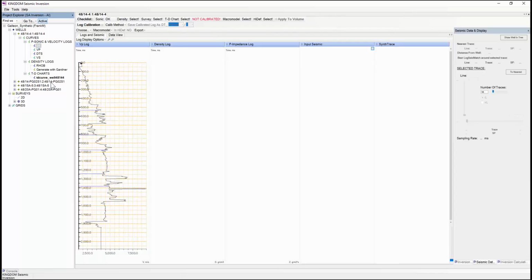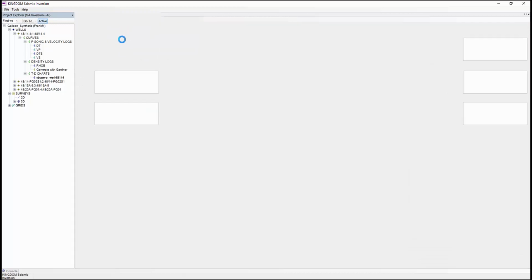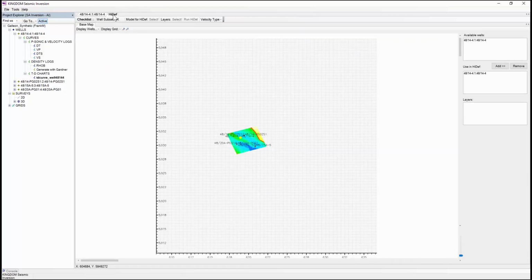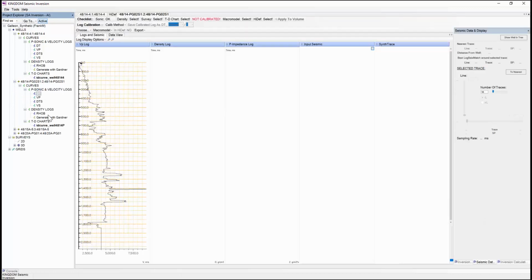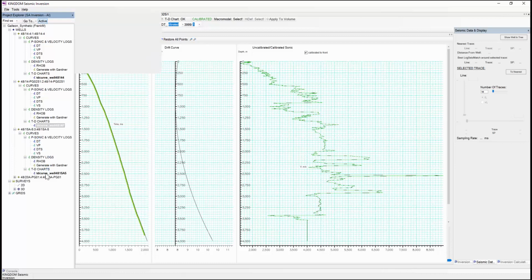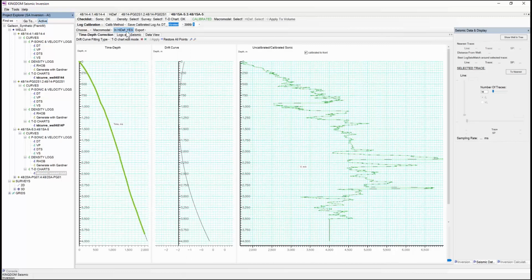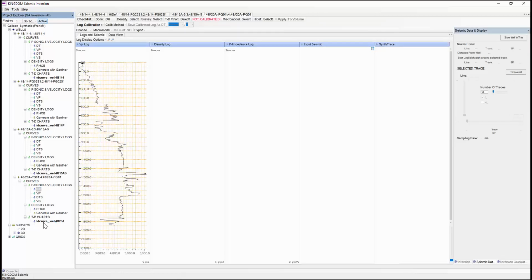So we're going to select the DT and then the time depth curve. And then you'll see the in high def button up here. We'll click that to say yes, and we have a high def tab go up here. And then we're going to proceed with our other wells, selecting the same option. So as we're clicking through, you can see that it's 3 clicks per well, and DT, TD, high def yes, and last but not least, just the same.